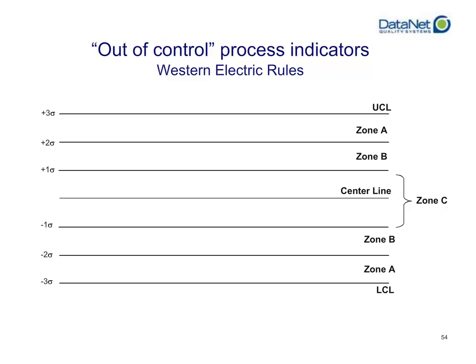First, a little bit of an explanation of the control chart that you're seeing. You're seeing an annotated control chart. You have 3 zones above the center line and 3 zones below your process center line. Each zone is defined by an additional standard deviation from your process center line. So zone C, where we expect the vast majority of our data to fall, is plus or minus 1 standard deviation from the process center line.